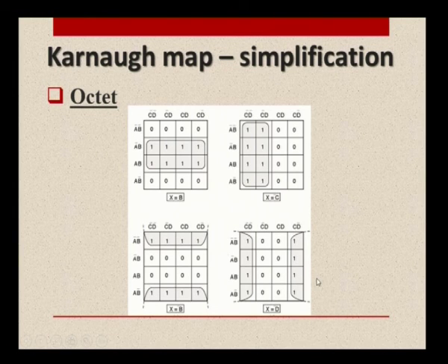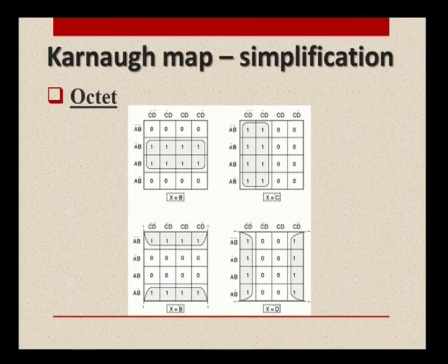One thing we can wonder about in this K-map: there are 8 ones written, 8 1 values. Each one term is represented by 4 combinational inputs. Like that, there are 8 terms in the original expression. But once it is identified as an octet, only B is the common thing for the entire octet, so that is the only thing written. So, the 8 terms get reduced to a single character B.